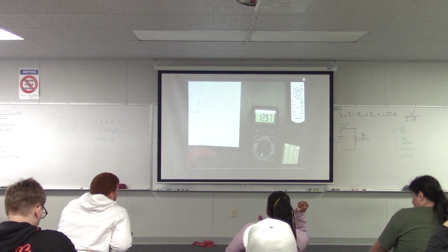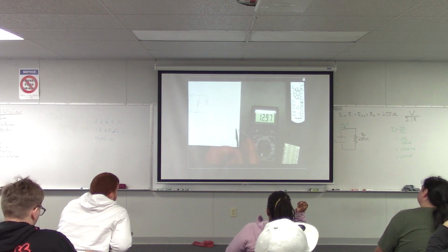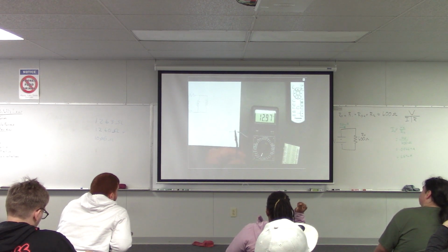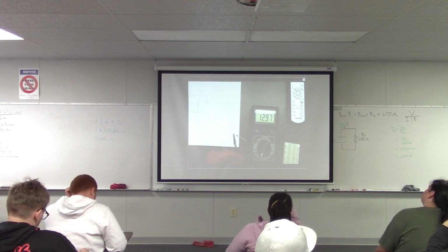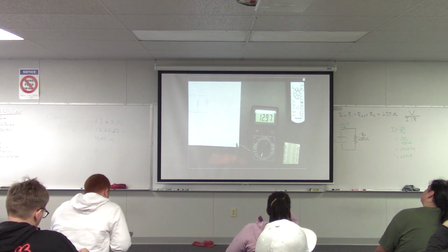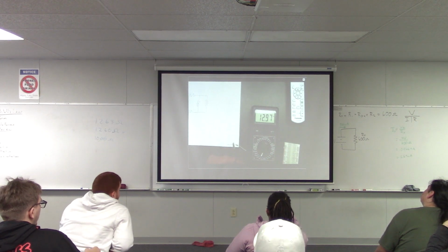So first of all, check the connection to your resistor, and if that's good, it means there's a problem with your meter or your leads. If you're in the middle of a test and you see something like that, just get a brand new meter and brand new leads. Just don't even futz with the old one, okay? Because you've got enough to deal with already.